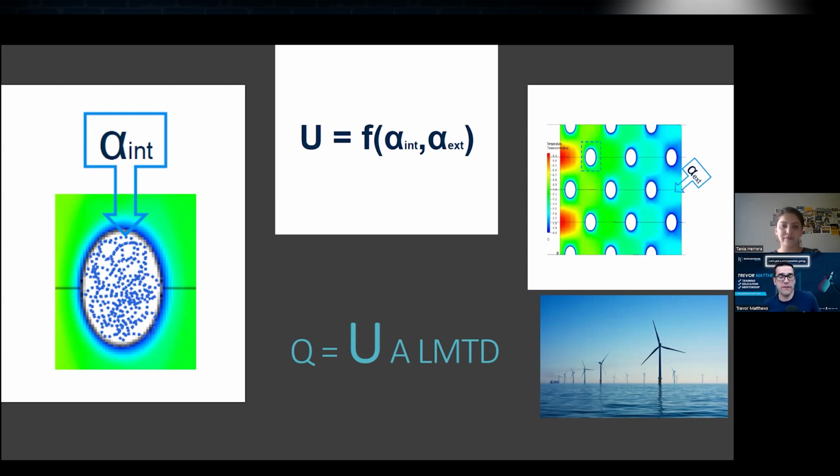Now a lot of new systems have capacity control, so they'll have a VFD drive on the compressor where we'll ramp up the mass flow and then slow the mass flow down of the compressor. So this will actually change that velocity in these coils as well as change the heat transfer? Well, yes, because I think that everything is connected. So what happens in one item will impact the other one.